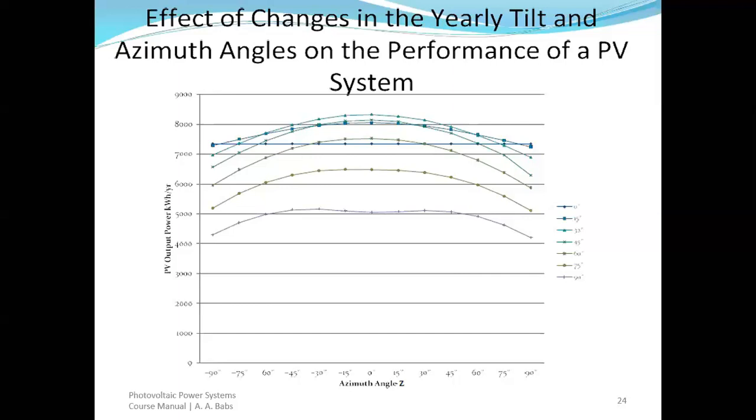So at different seasons of the year, we have different optimal tilt angles to get the best performance from our solar PV plant. However, when you have a small PV system installed, you can be varying the tilt angles, or you can even install a tracker that would vary the tilt angles at different seasons of the year and time of the day, right?